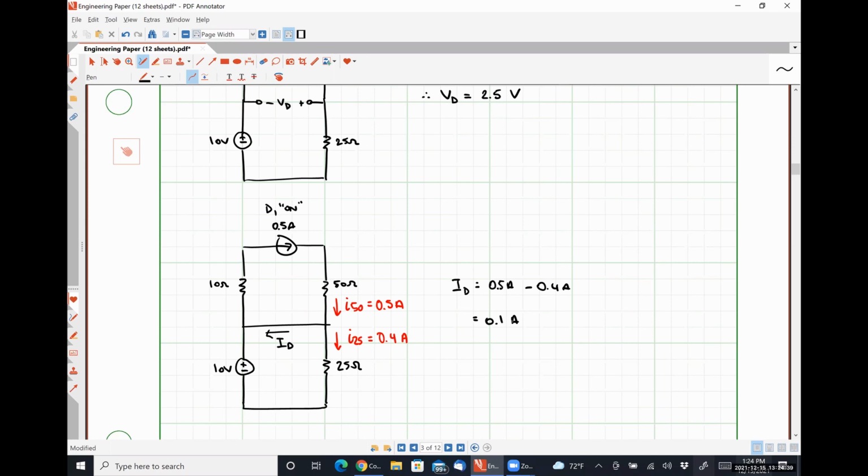So it's not horrible, but it's not great. Let me double check that. Yeah, 82.7 milliamps. So it's off. It's about 25% higher than it needs to be for this particular example.